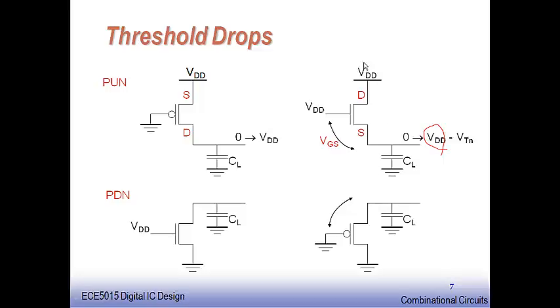That is the reason why, though using an NMOS device at the top and a PMOS device at the bottom can give a good buffer instead of an inverter, the output voltage is never going to be fully VDD, and it's never going to be fully zero, as I am going to discuss for the pull-down case, assuming a PMOS is connected in the pull-down network. We will continue with that.